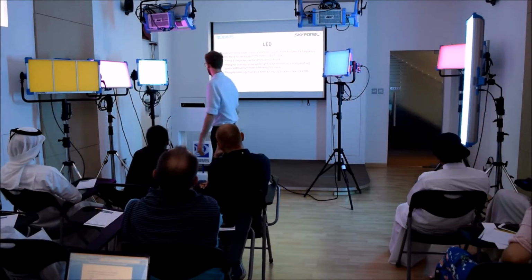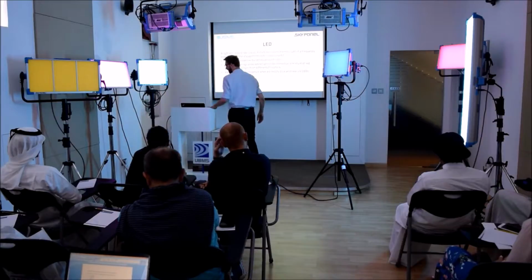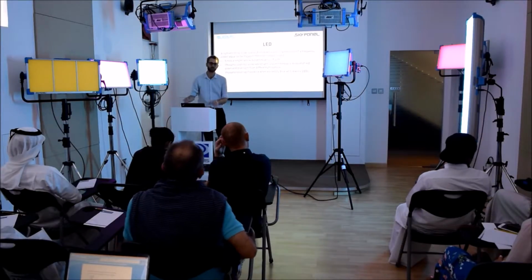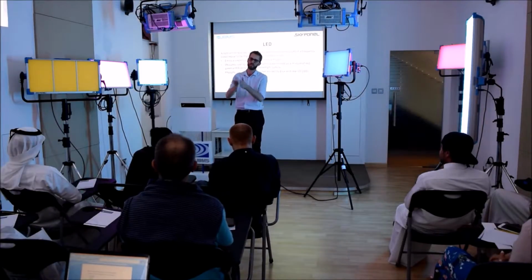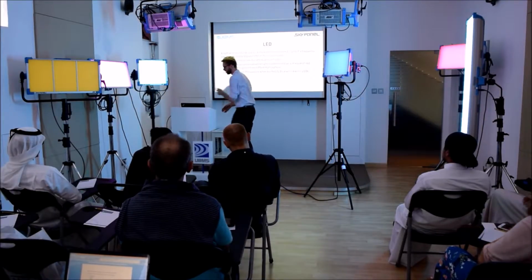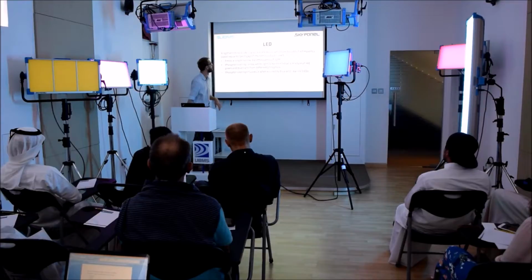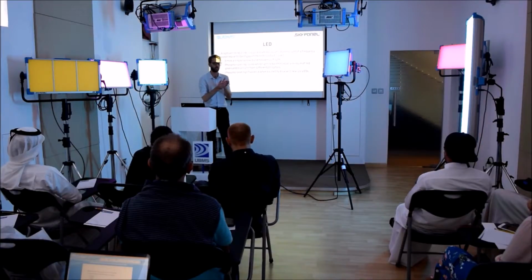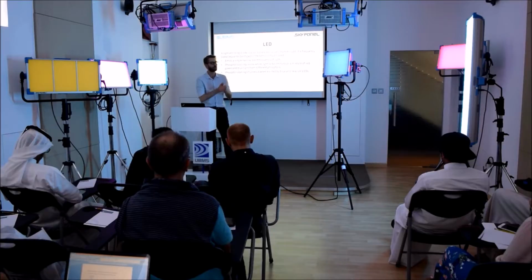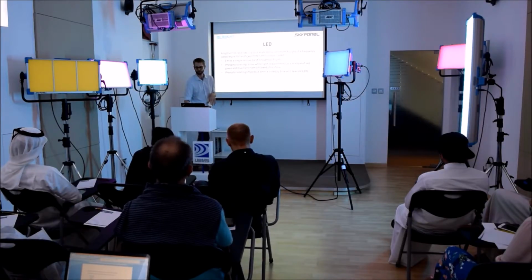Whenever you look at lights that say they are remote phosphor, they're remote phosphor because the phosphor panel is separate from the LEDs. We're going to look at this a little bit more. Sometimes the phosphor is not a separate panel, like on this light, but is part of the LED, on the same chip as the LED. That's the other way of doing it.